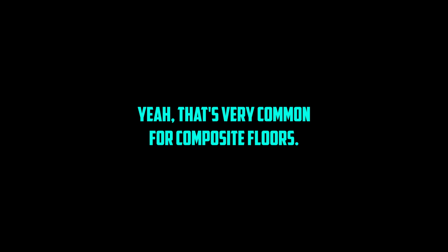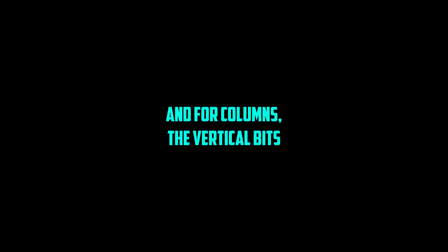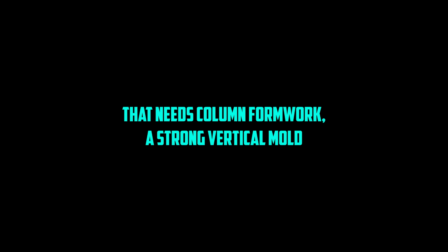What about using that profiled steel decking for floors as permanent formwork? Yeah, that's very common for composite floors. The profiled galvanized steel sheets act as the formwork, and the indentations create a bond with the concrete poured on top. The steel then works with the concrete structurally, providing tensile strength, though you still need reinforcing bars within the concrete slab itself. And for columns, the vertical bits. That needs column formwork.